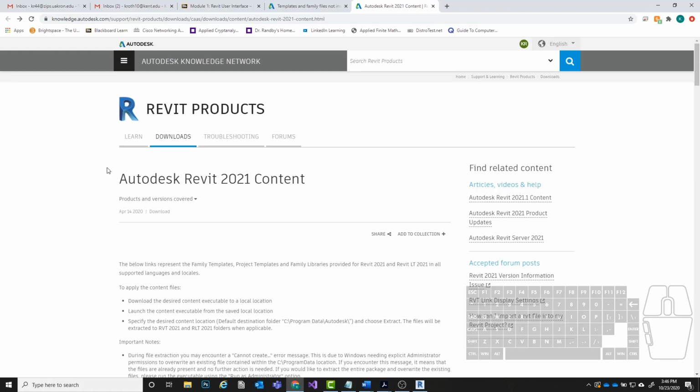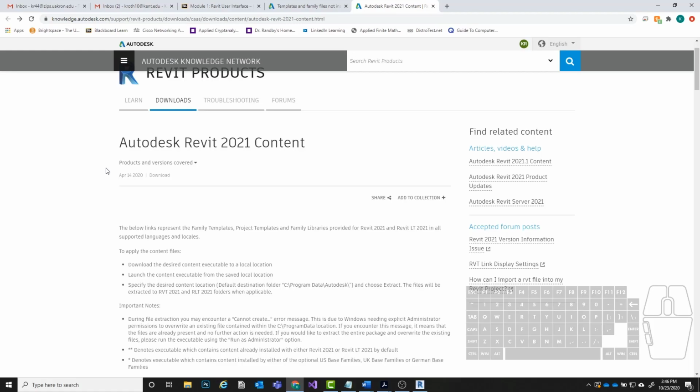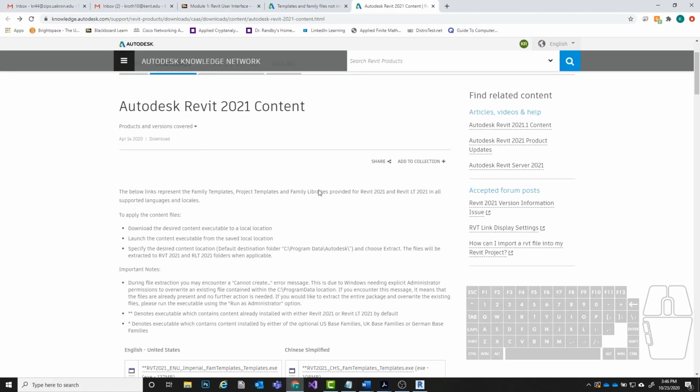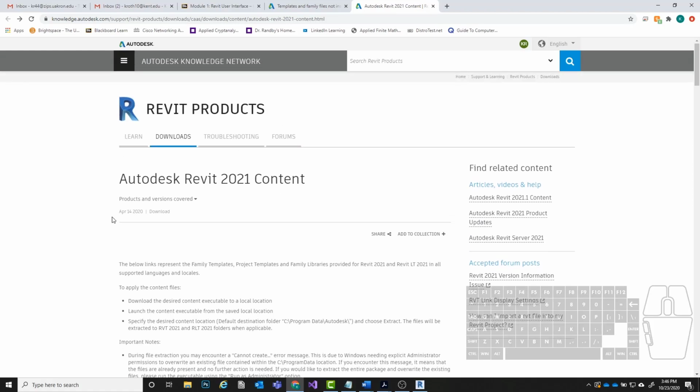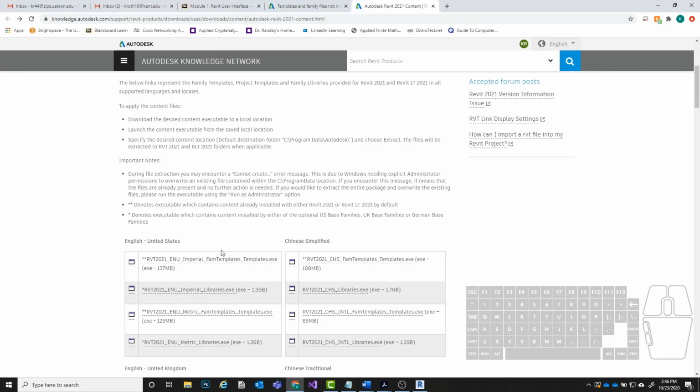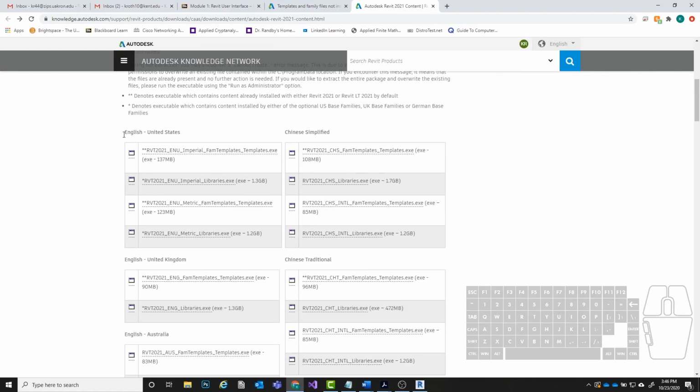That will be attached to this video, so just look on Blackboard either above or below this video. There should be this link added in there. So on this Autodesk Revit 2021 content page, you want to scroll down here to where it says English, United States, and you want these 2 files right here. You want this Revit 2021 Imperial Family Templates file, okay? And then you want this one that says Revit 2021 Imperial Libraries, all right?